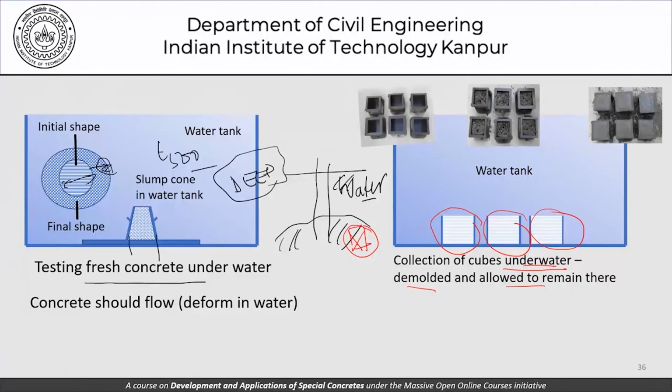Of course, for the purpose of determination of strength, they'll probably have to be taken out and the strength determined. So that is where a small balance between the practice and the reality, a balance between the theory or the ideal situation and the reality, can be struck. We cannot possibly test the concrete underwater. We'll take it out momentarily, for a very small period of time, and test it in air, but at least the sampling and the curing happens in water, the sampling particularly.